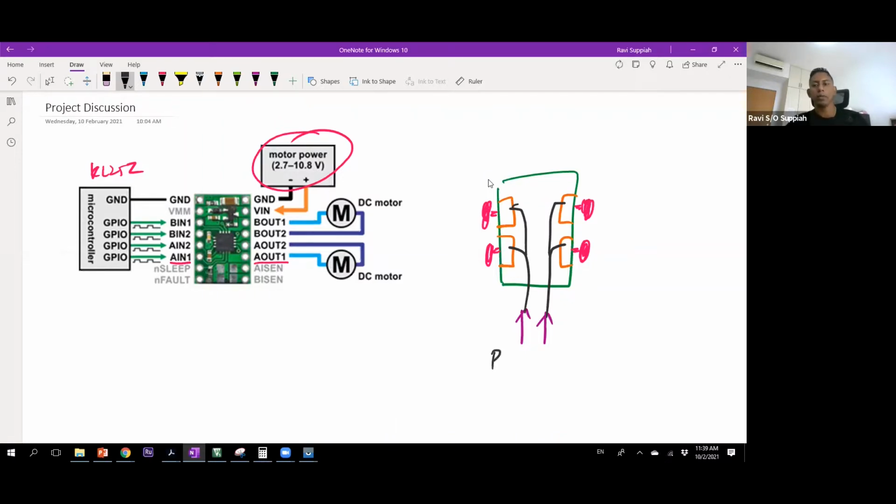Okay, so you can say this is your PWM left and PWM right. So you can imagine that even though I have 2 left and 2 right, you imagine it as 1 left and 1 right, and the same PWM signal is coming out. Of course, when you say PWM left, PWM right, this is actually 2 lines each, because you need to be able to move in both directions, forward and reverse. Correct. So this is one possible option that you can use to configure your motors.